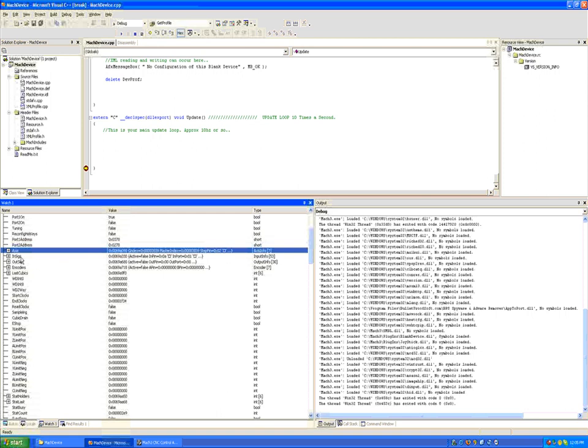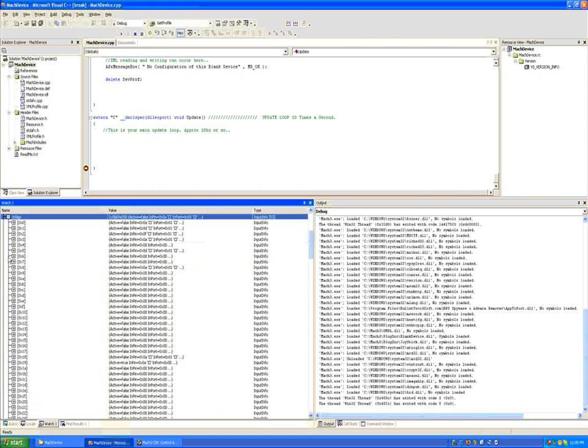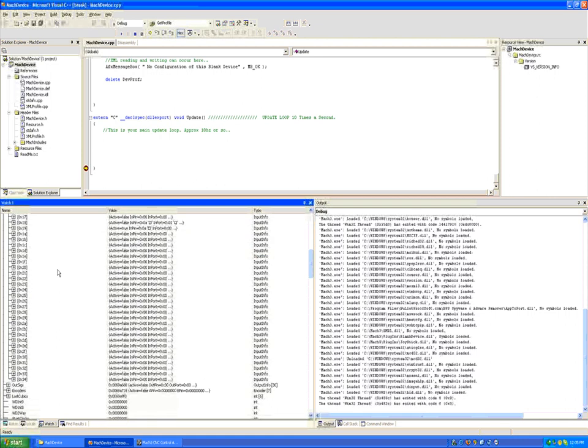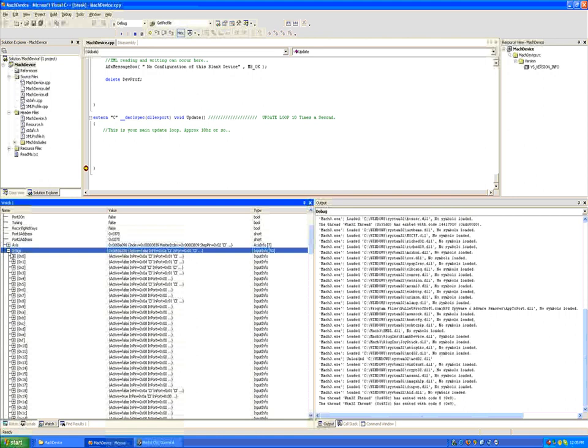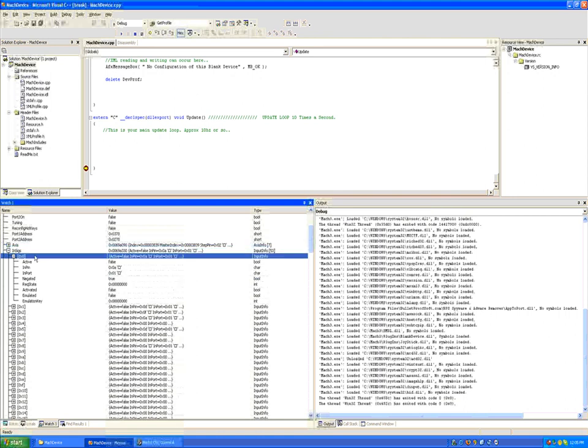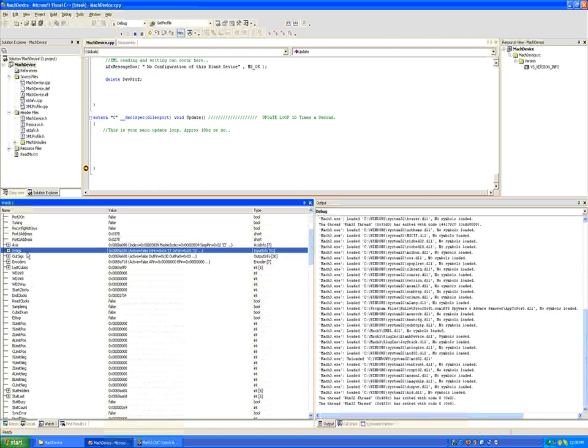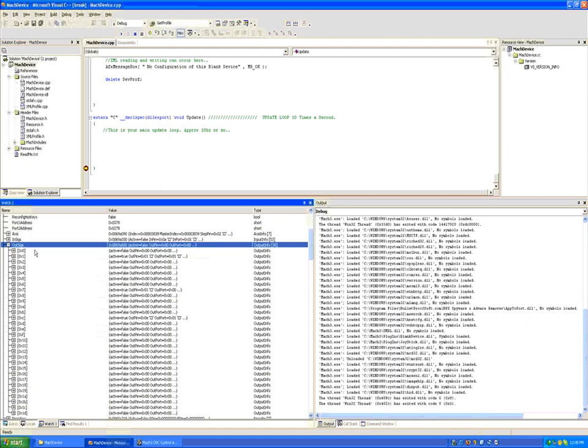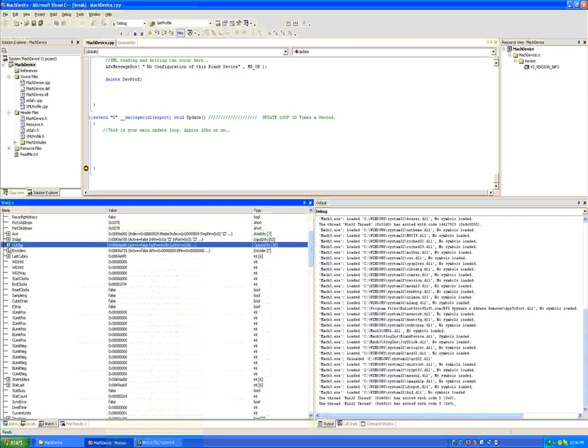You can see we have a variable in the engine called insigs. Insigs is a list of all the input pins. You can see that there are hex 34 of them, and each input, for example, input 1, we can tell whether it's false, what pin it is, what port it is, whether it's negated, its required state, it's activated, it's emulated, and what its emulation key is. So there's a structure for each input signal, and there's a corresponding structure for each output signal.